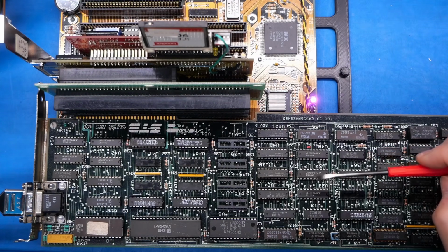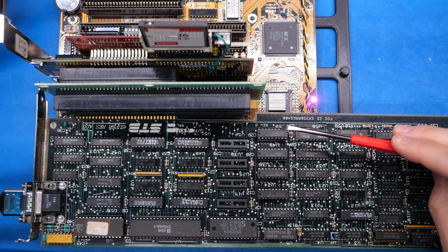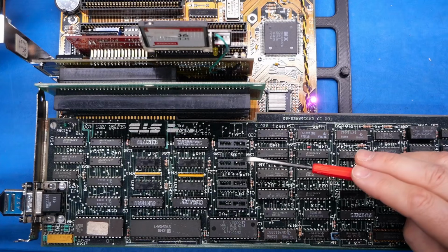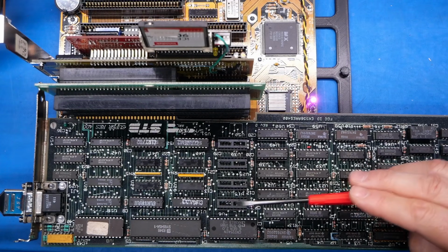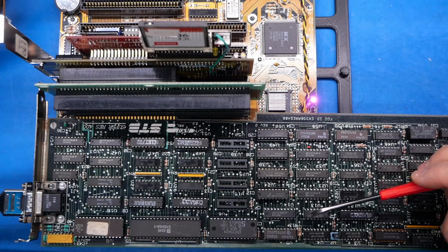Now, one of the things that we're unable to test on this card is the additional RAM on here. We don't have any access to those higher graphics modes. We might be seeing that same problem on these bits over here, which are probably connected to the same 374s, which I think are all just latches.